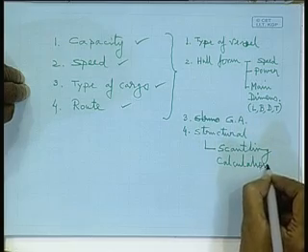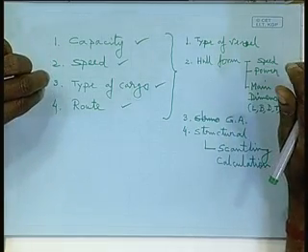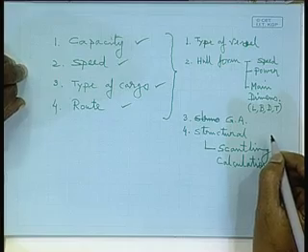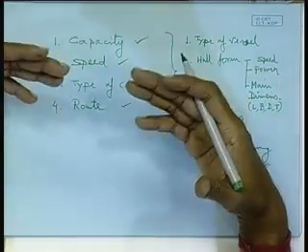That means, once stage 3 is over totally, your hull lines, the form of the vessel, the principal dimensions, everything has been frozen. You are not going to change that. Now you have started detailing on that. The first phase of detailing is the scantling calculations. Scantling calculations means you start with calculating the plate thickness, section dimensions, stiffener dimensions, etc.